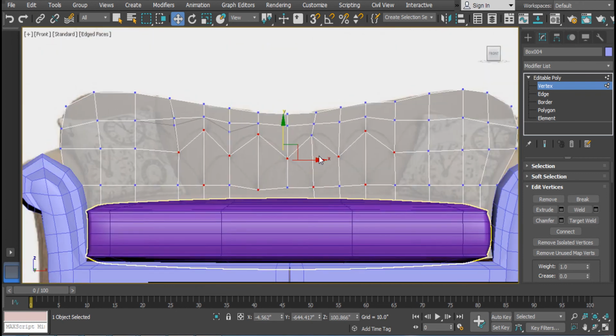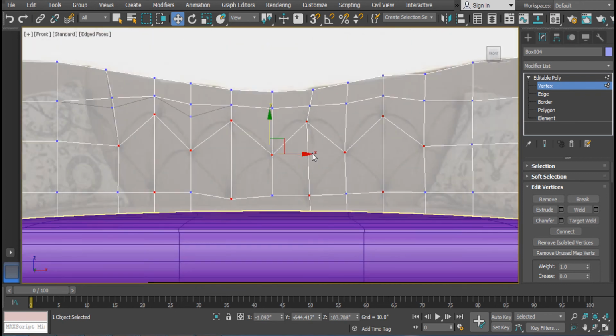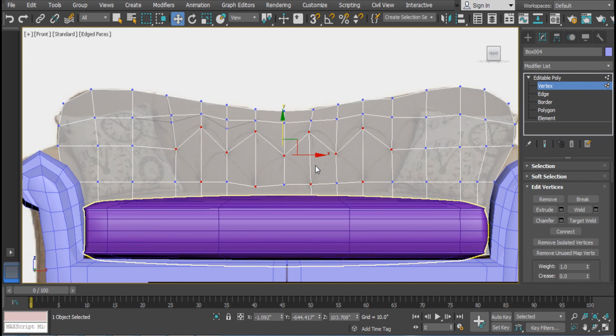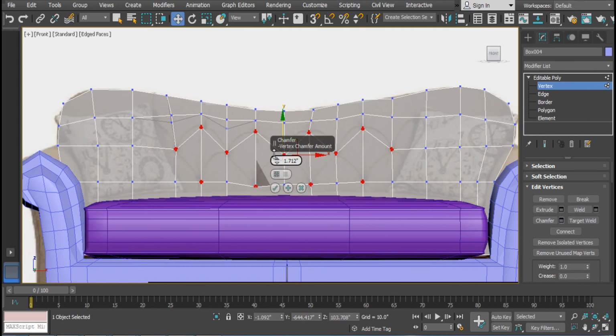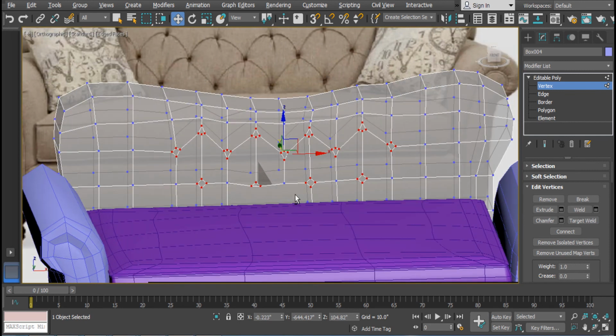In the layer editor, there is an option, with the left mouse button, properties. There is an option called backface color. Once you click on that, you will find it easy to work in the viewport. Here I am not using it, but you can use the backface color technique.